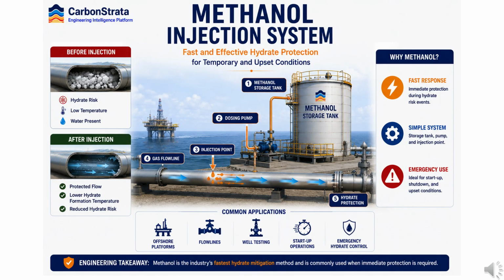However, methanol is generally not recovered after use. This can result in significant operating costs for continuous applications. For this reason, methanol is often viewed as a flexible short-term solution rather than a permanent hydrate management strategy.